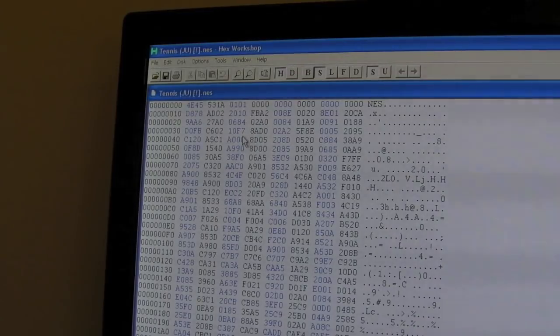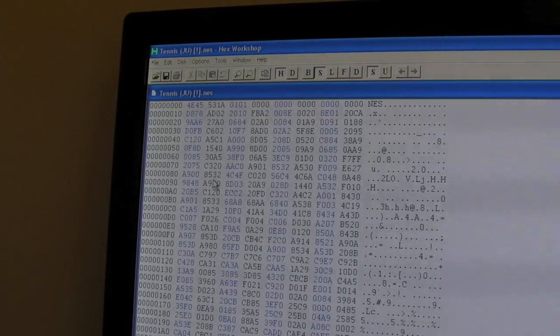Something else worth pointing out is that the relationship between the ROM file and an emulator is going to be different to the actual ROM image, the physical binary, the code that we were running on the emulator, that's going to sit in a chip on a cart somewhere. Now in the NES, you've usually got a couple of chips. This is something I'd forgotten about. It's only when I've looked at the physical side of the NES and the Famicom that I've realised there's a couple of chips in a lot of scenarios. So you have the program code and the character ROM, which is used by the PPU, the graphics, and would be on a PPU ROM chip.